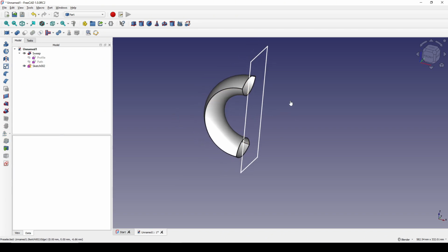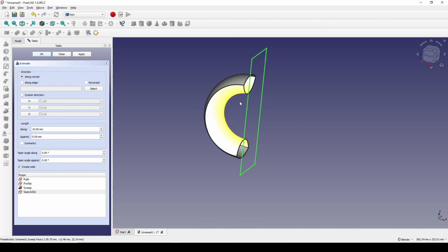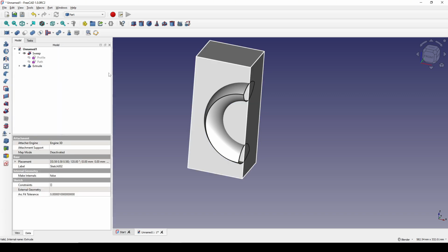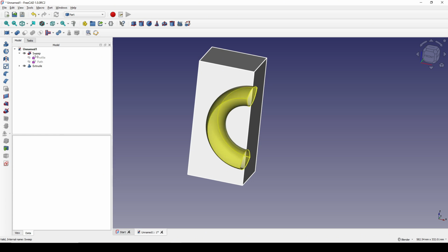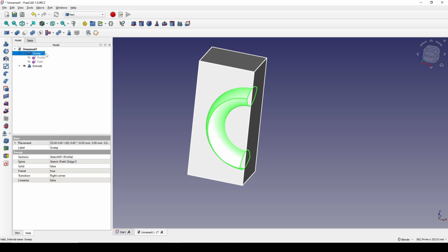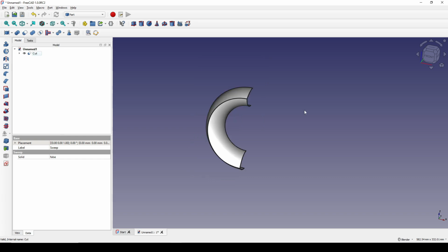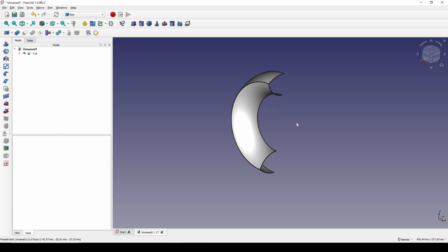And then I select this sketch and I extrude. Extrude this one in the negative x-axis. And let's try 100. Okay. Now I control select the sweep first, the one I want to keep, and then the extrude, the cutter, and then I go to the cut. Now we just remove the back of this surface.